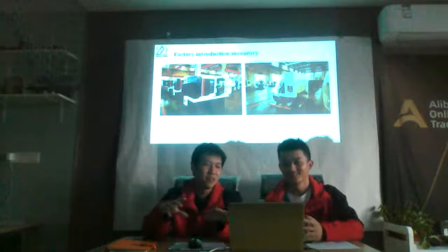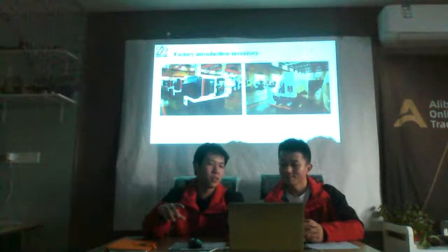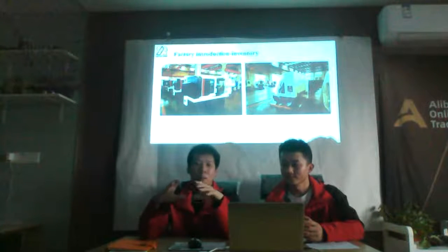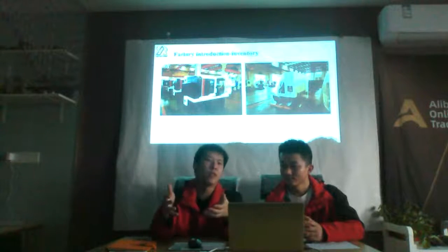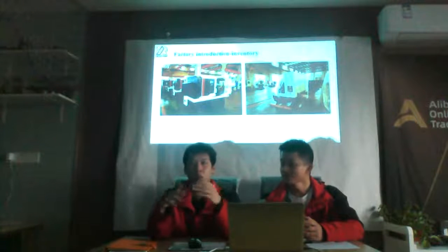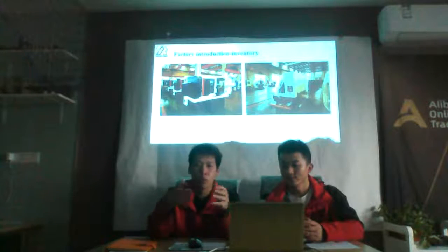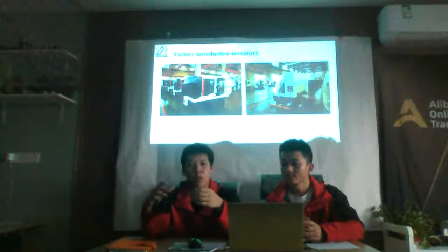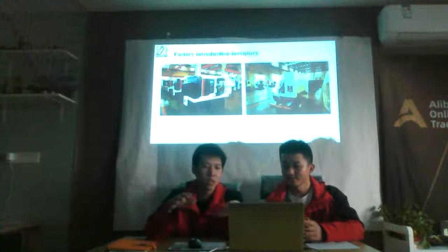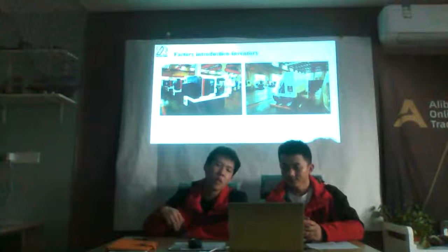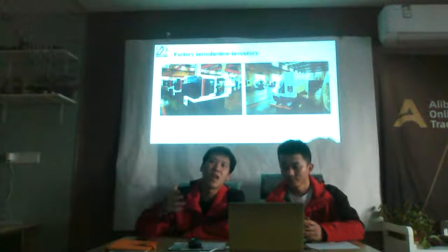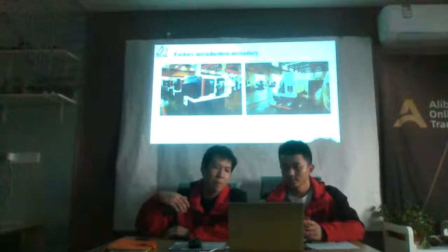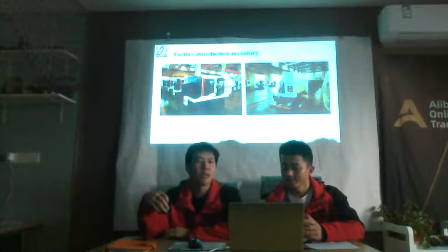And first step, we use this type of plastic bag, like the one you see in the picture, to cover the machine to make sure no dust or water moisture will go inside the machine to damage the metal components or metal structures. And after this, we do another very tight, very smooth plastic wrap to wrap the entire machine body.